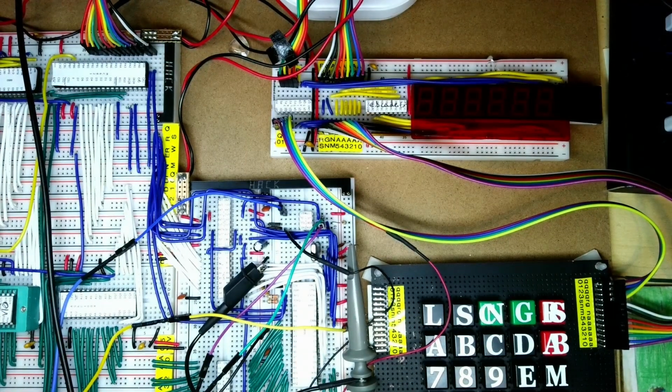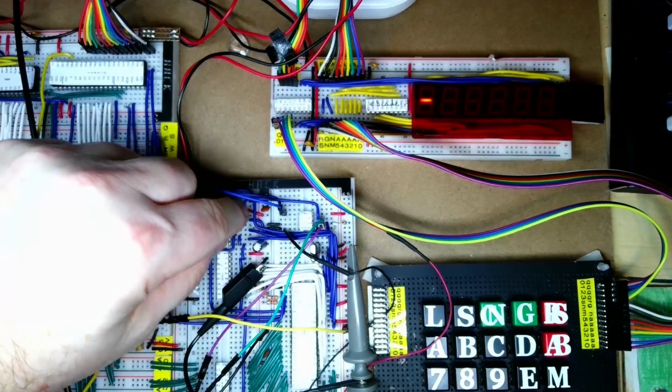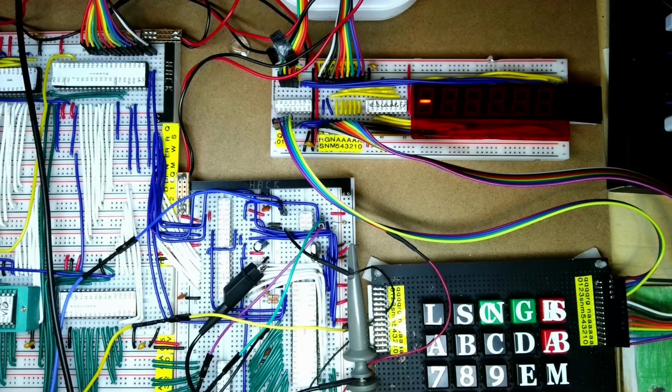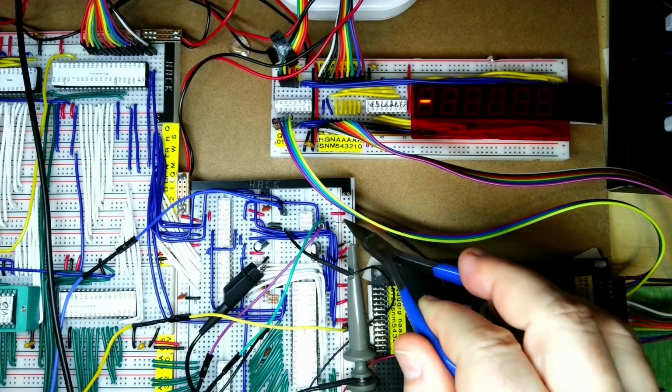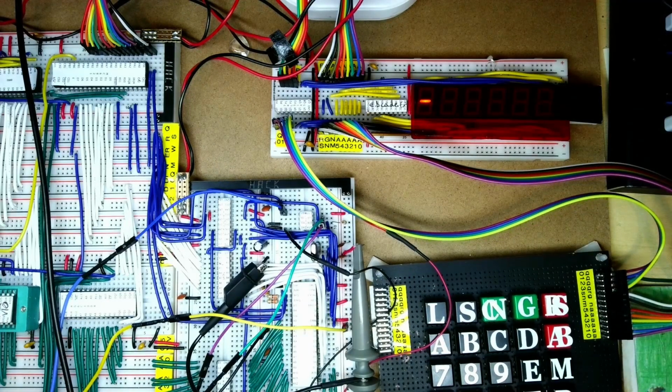So all I'm going to do now is plug that signal back in, and we should see that this no longer resets. So the reset circuit's working. It was a little bit more complicated than I anticipated because I didn't realise we needed this pull-up resistor here, but now we've got the pull-up resistor, everything seems to be working fine.